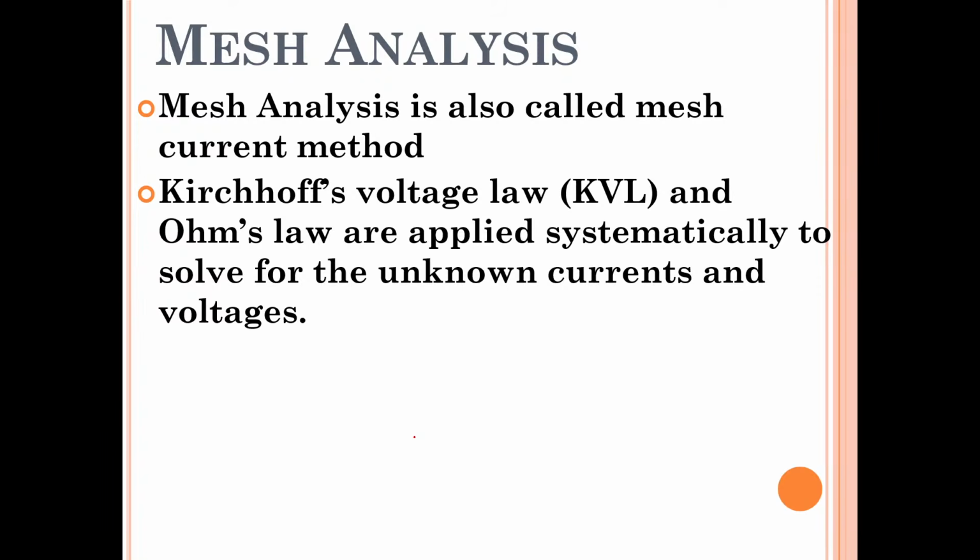If you want, you can note it down. There is a specific procedure that is to be followed for mesh analysis. First of all, we have to identify how many meshes are there in the given circuit or network, and we must assign mesh currents within each mesh, either in clockwise direction or anti-clockwise direction. After that, after assigning the mesh currents, we have to determine the mesh current values by applying Kirchhoff's voltage law and Ohm's law.